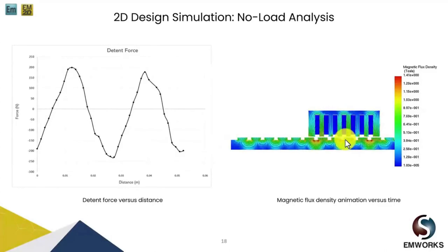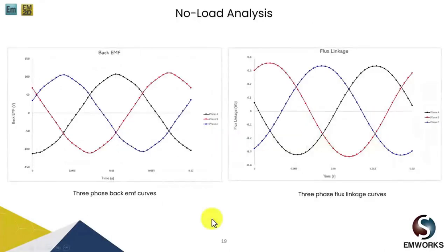and improve the efficiency of your machine. Next, we again obtain its back EMF and flux linkage, and since, as we have seen, the air gap has been increased, the overall coil flux linkage has reduced compared to the flat type. But overall, anyway, we cannot compare both the motors together, and we get its back EMF around 100 volts.